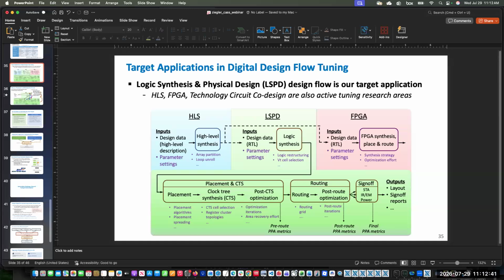Another one might be this: typically in this flow, we just go through the place and route tool and look at the results there. I would look at maybe two things. One would be the complexity of the sign off. How do you actually prove that the results are what they are? Another might be to phase in some hierarchical design. That's a key skill that's not taught as often.